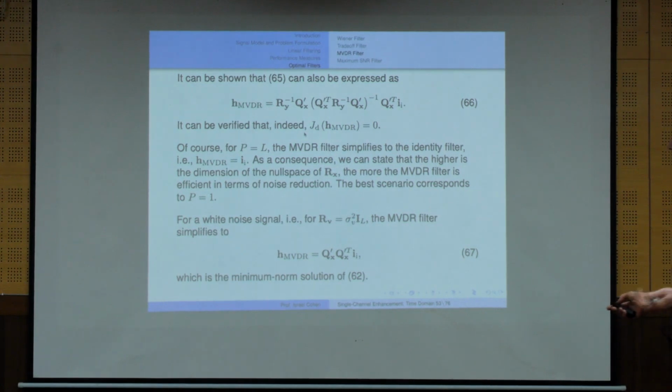which we need to estimate based on the noise, in this expression we see that once we know the eigenvectors that diagonalize Rx, we can use something adaptive, for example, the correlation matrix of the measurements, because sometimes it's easier to find the correlation matrix of the measurements based on received data.